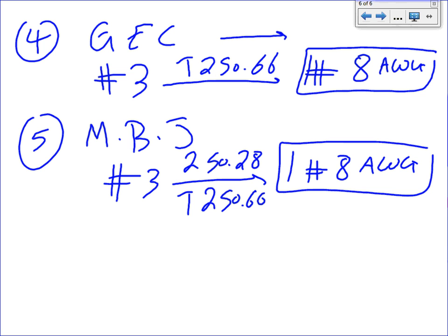Now my question for you guys: if you have a shop with some lights, receptacles, and some HVAC equipment, and you need to size the main, what do you do? You do the calculation that we did for all the welding equipment, do the lighting calculation, the receptacle calculation, and the HVAC equipment calculation, add all of them together, and size your main.